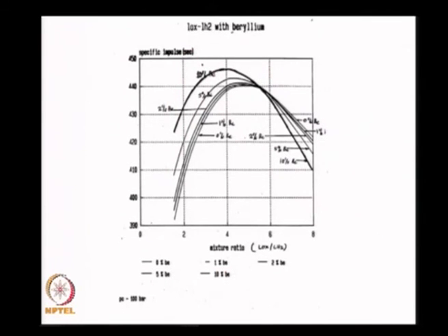And the last slide which I wanted to say was, when we consider a solid propellant, we added metal to solid propellant to improve the specific impulse. But if we try the same thing with liquids, what happens is the molecular weight of the products goes up, and putting metal in the propellant rather than improving the performance does not really give the advantage like you have in solids. Therefore, metal in liquids does not seem to be a solution.